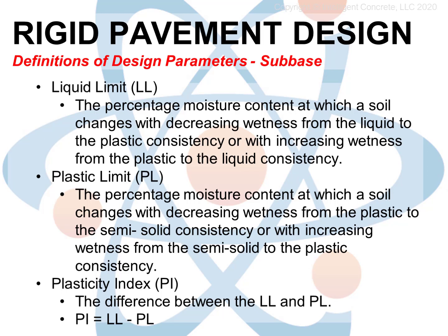You keep adding water to it, a couple of drops at a time. You'll feel the soil gradually start to be able to be molded and remolded instead of just breaking up. Some soils will do this readily, others not at all. They just go from being a crumbly soil to being mud without an intervening plastic state.